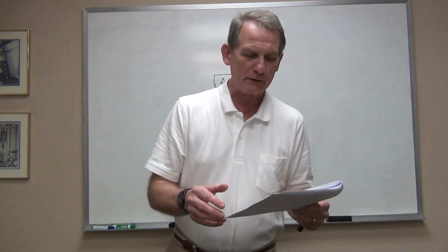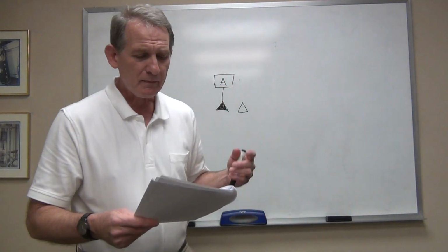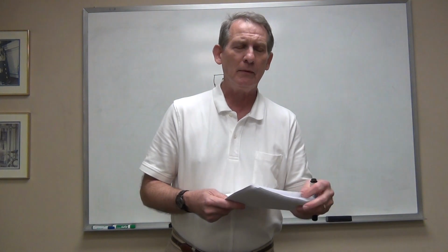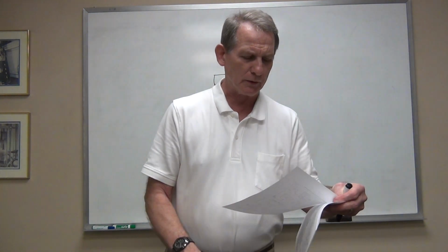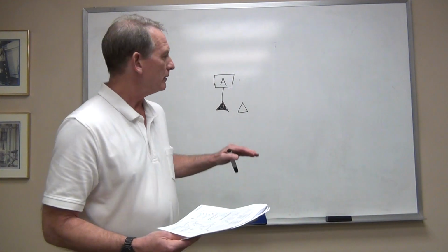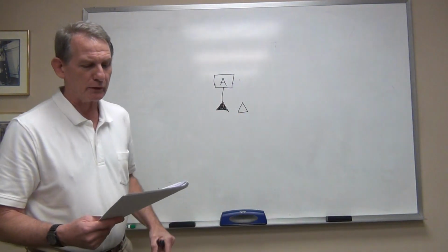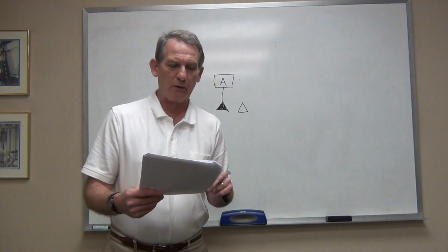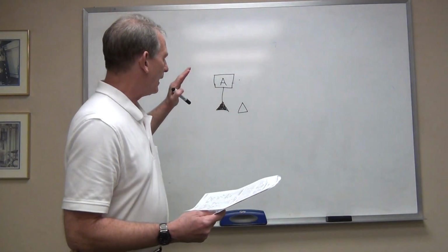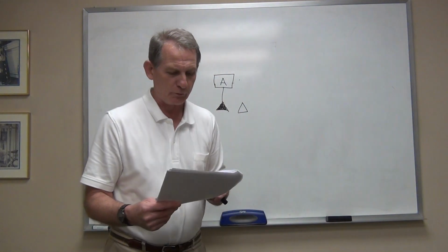You'll never see them mixed like that. I don't know why they even make the distinction. It may have been because of limitations of CAD systems or something. I don't know, but that style, either filled or unfilled, is completely optional, and it means nothing. It still is simply an attachment point for the datum.